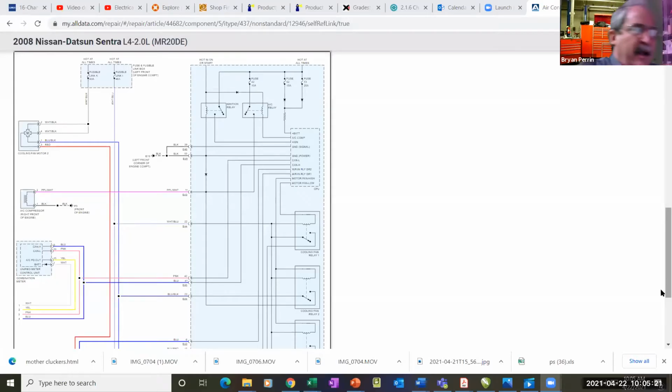So it's really hard without a factory, I don't mean a factory level scan tool, but a scan tool that you're able to go in, whether it's a Snap-on or a TEL, something like that, where I can go to manufacturer specific. Because then what I can do, and I've done this on your Nissan, is you go in and you can talk to the climate control module and you push the button for AC request. And it goes to yes. Okay, so that is working.